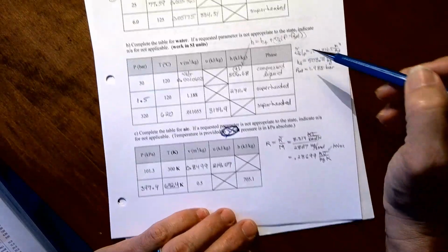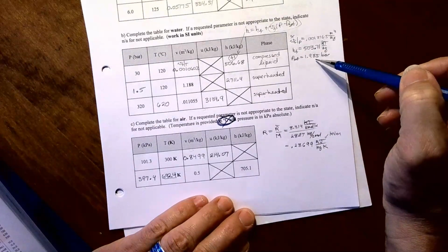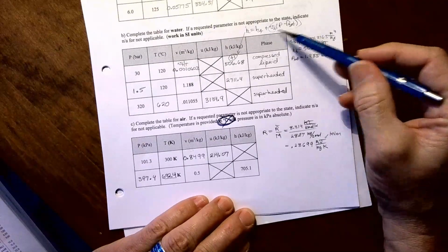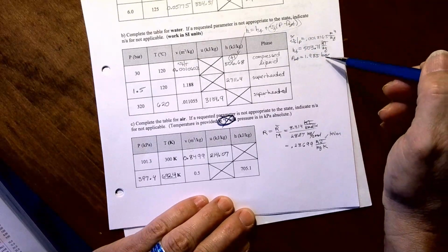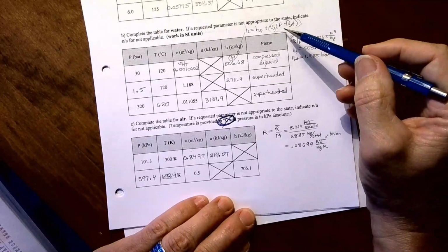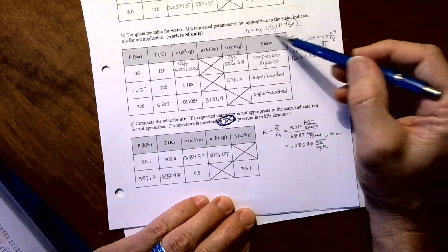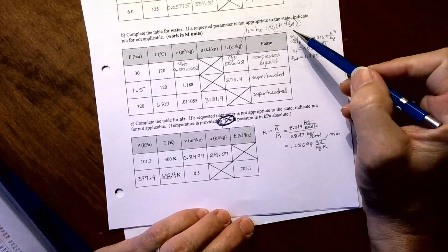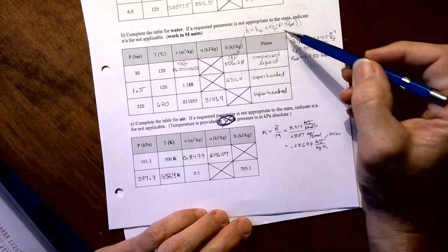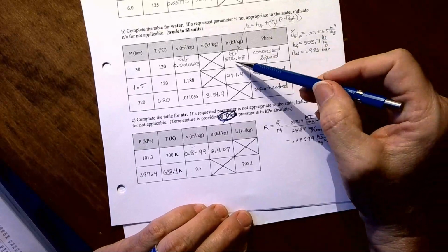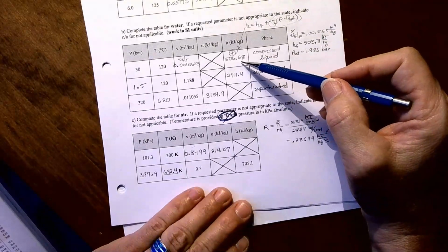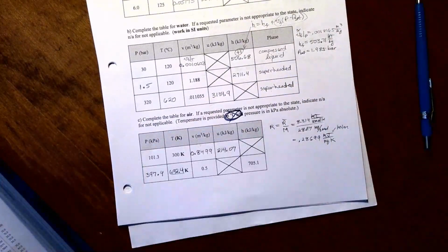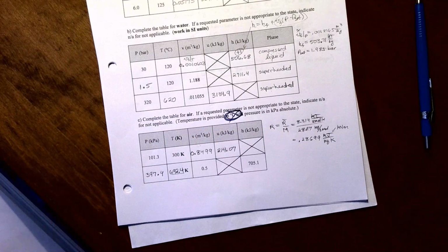The saturation pressure is 1.985 bar. And then we have to remember that these units have to be converted. So you have to leave bar, put it in kilopascals, and then this will end up being in kilojoules per kilogram. And so there's a small adjustment of about 2 or 3 actually because of this term. So the correct answer is 506.68 for h. Some of you used the compressed liquid water table, so I'm going to go find those quickly.